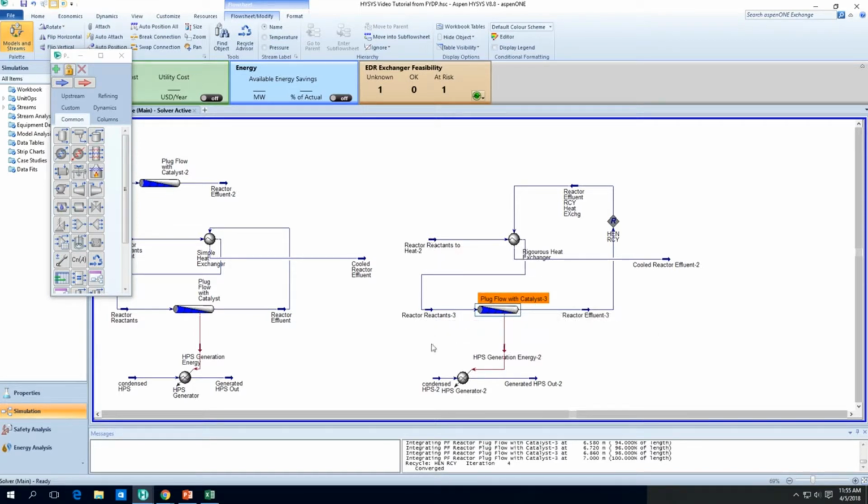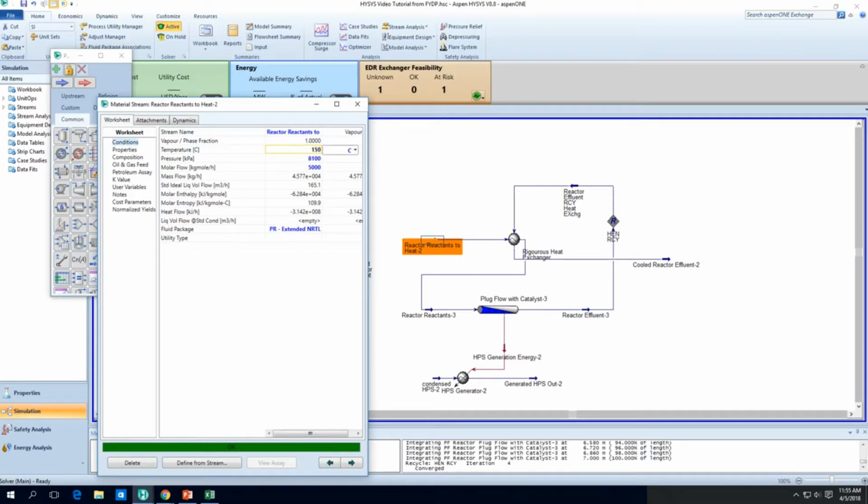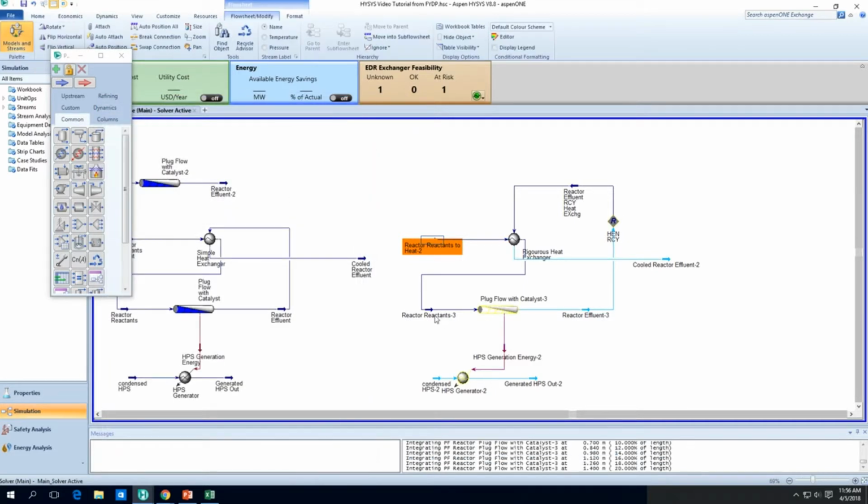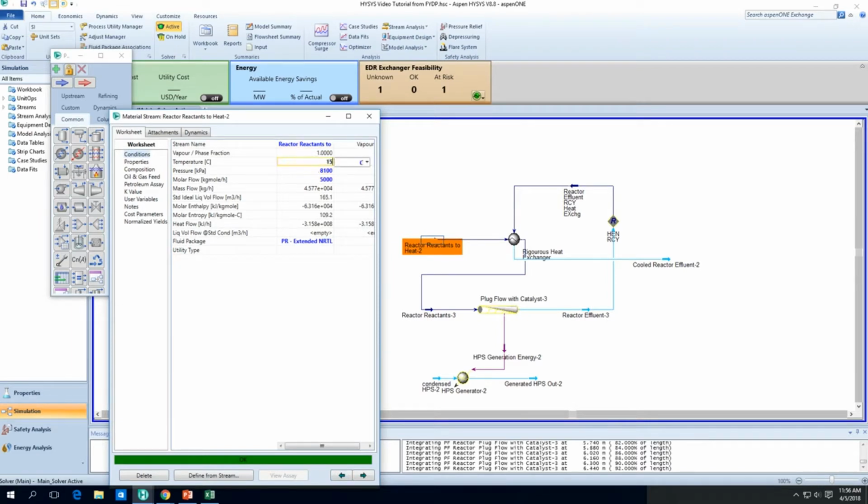Okay, so we want to let it match this reactor thingy, so we'll make it lower a bit, 150. So we are taking heat out of the system, so as to cool it down. Okay, so it looks like 150 is too much, in fact too low. So we'll probably let this fella iterate a few times to see what happens. That's way lower than what we want. So let's increase the temperature to about 155 and see what happens.